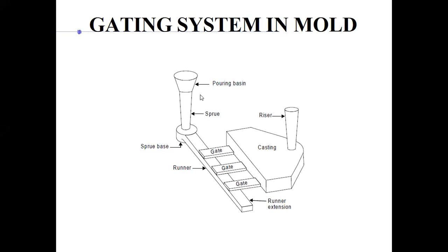Okay, you see, once the molten metal starts flowing in from this end, right? Because you have the molten metal flowing from top to bottom, right? The velocity would increase, isn't it? So if the velocity increases and you have the same flow of molten metal, then as per, I believe you have studied fluid mechanics, as per the constant discharge, that if you want to have the same discharge, Q is equal to constant.